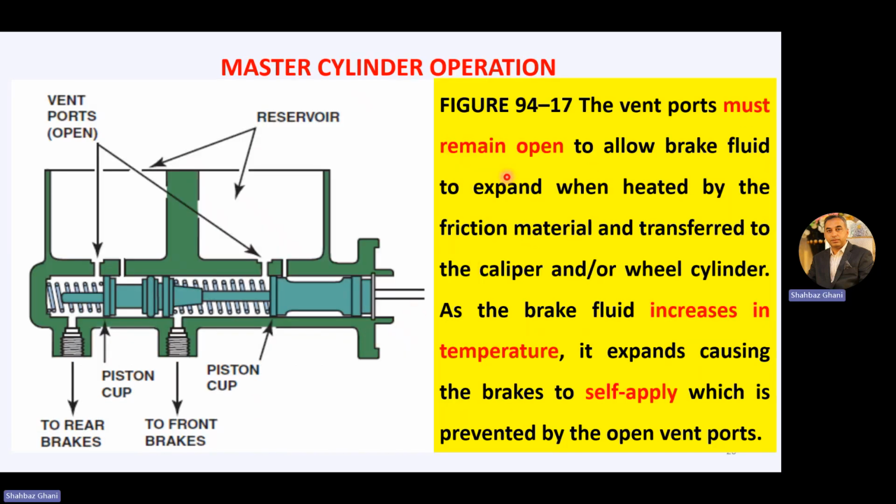I have briefly explained the function of this brake master cylinder. Now, once again for your better understanding, this is the end where we get force or pressure, foot force. When we apply the foot pedal, the force goes to the vacuum booster or power booster. From the power booster, that force is applied here on the master cylinder. And in the master cylinder, we have this piston here and this piston here. And there are 2 openings.